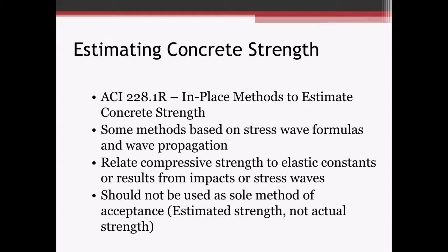These methods should not be used as the sole method of acceptance. These are all estimated strengths. These do not give you actual in-place concrete strength. The only way to get actual in-place concrete strength is to take a core.